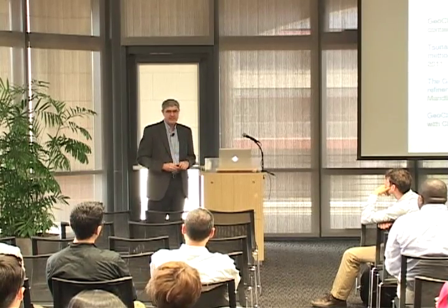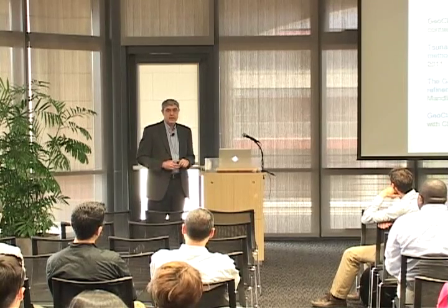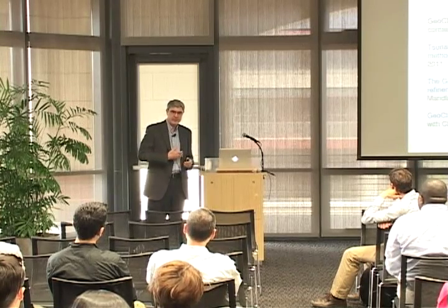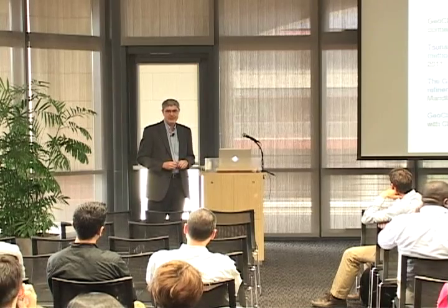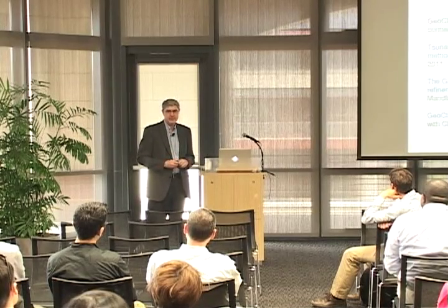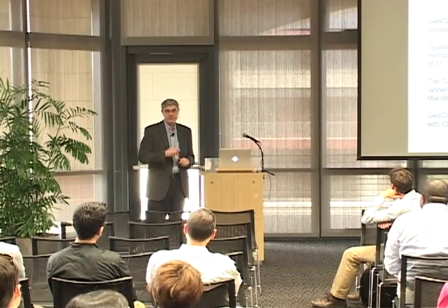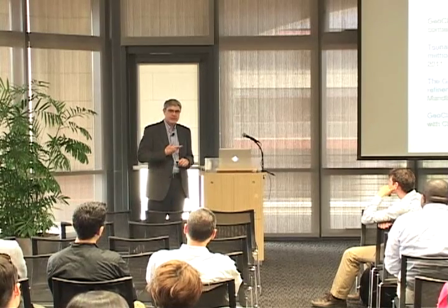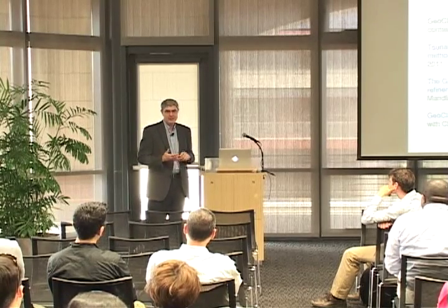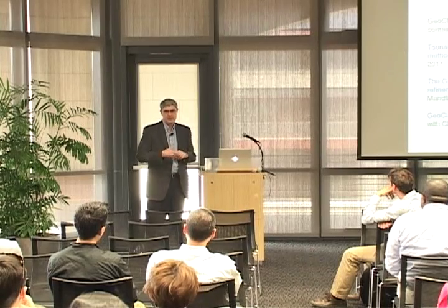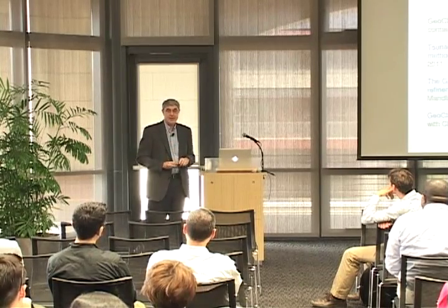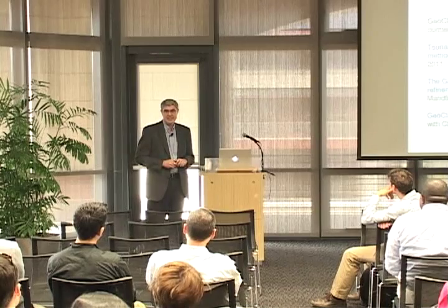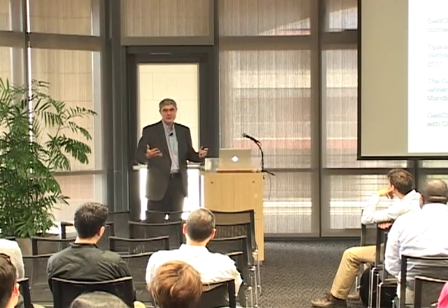In terms of the tsunami modeling, there are certainly some tunable parameters in the model, but there's actually relatively few. One of the big ones in terms of inundation is the friction factor. In the shallow water equations, we use a Manning friction coefficient in the momentum equations that has some coefficient times some term that gets very large as the depth gets small. As the flow gets very small, this friction term kicks in, and at some point it's going to stop the flow. And there are tables of what a reasonable Manning coefficient is for various kinds of surfaces, for sand or gravel or brush or trees or whatnot.